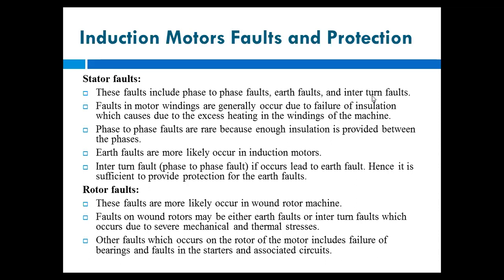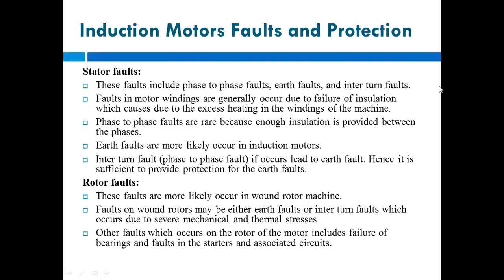So if any fault occurs in that starter, then also we have to protect the motor. And associated circuits means if any fault is occurring in the circuit, we have to protect the motor by using relays. Okay, so these are the faults occurring in the induction motor: stator faults and rotor faults. Stator winding faults and rotor faults. If you consider the rotor, you should imagine the rotor construction. Then you can imagine the faults occurring in the system. Okay.